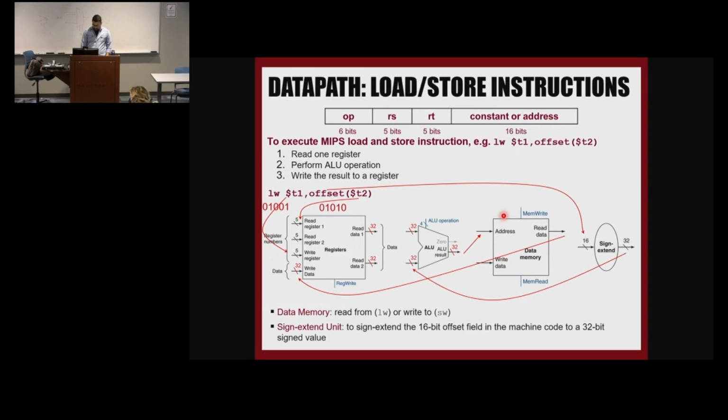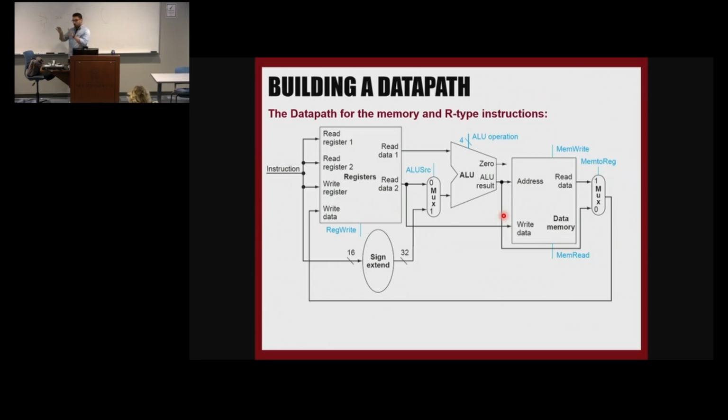Okay. So now if I put all these blocks together, this is what you can see here. I have an instruction. Forget about this part. We already talked about the fetch, which had instruction memory and the PC, and the PC plus 4 calculated. This is what happens after that. We have instructions. The 16-bit part of the instruction goes to the sign extension unit, and then it goes to the multiplexer.